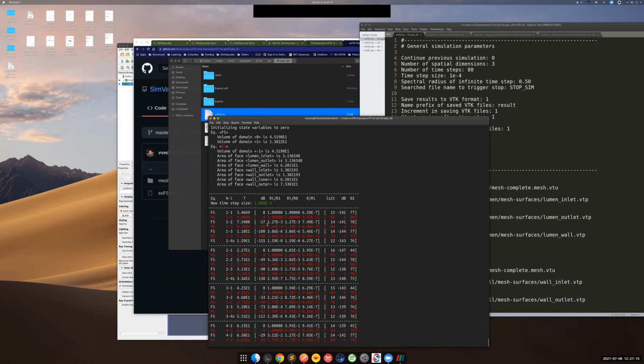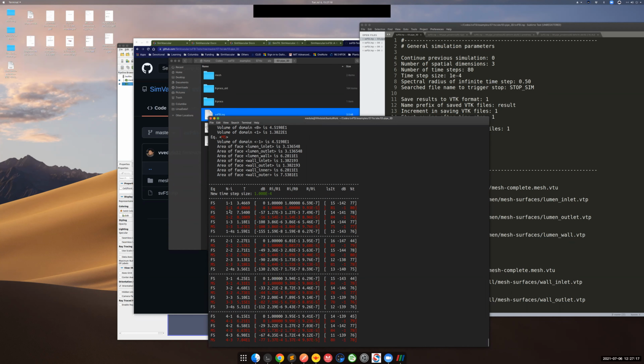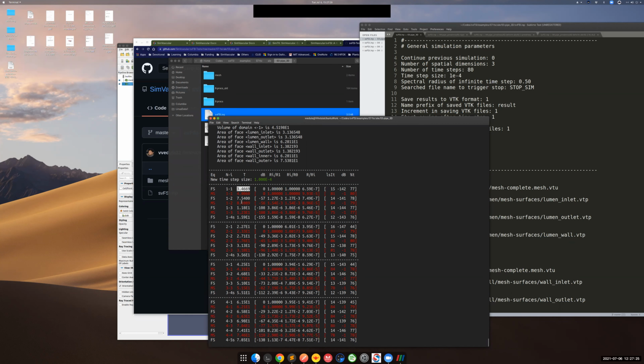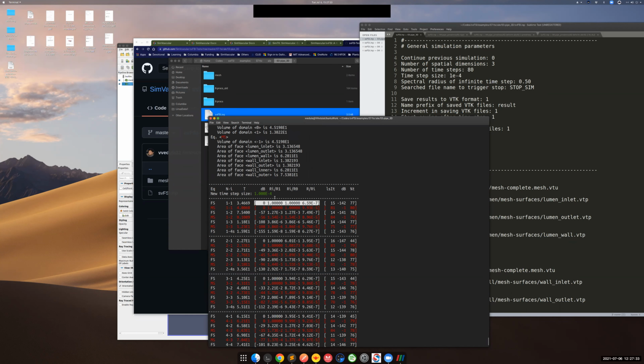Now, here there are some numbers. So initially you have the time step and the nonlinear control, nonlinear step here. There's a 1, 2, 3, 4. Then this column represents the time taken, time elapsed for each time step. And then this one represents the nonlinear or Newton solver convergence. So for instance, Ri over R1 is the ratio of the current residue to that of the residue at the beginning of the nonlinear iterations. Ri over R0 represents the current residue ratio to that of the initial residue. And this one represents how the solver has converged.